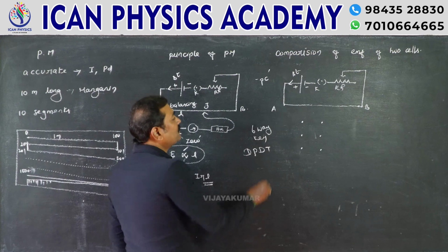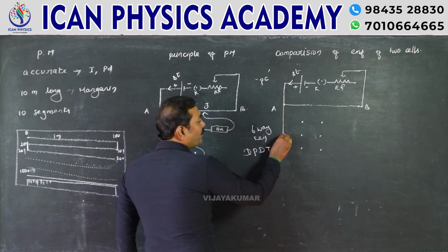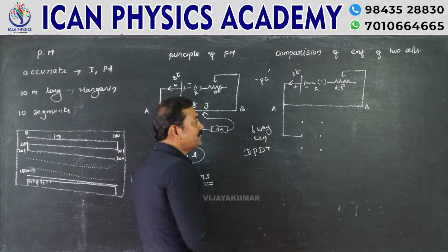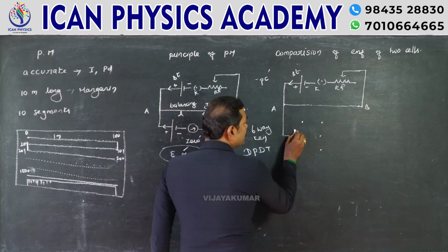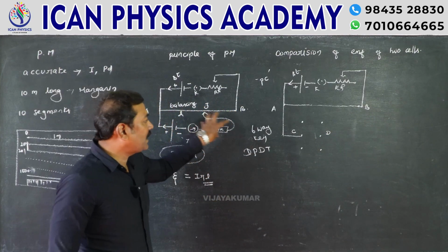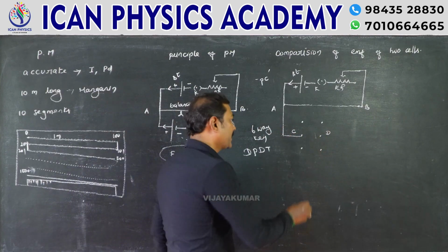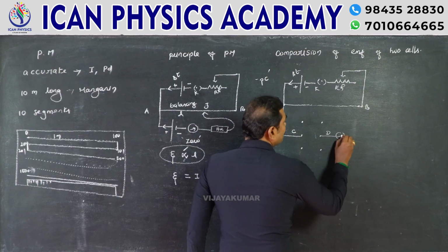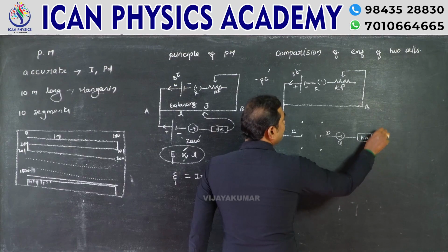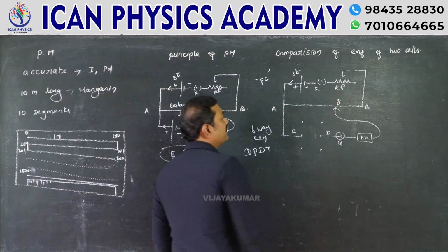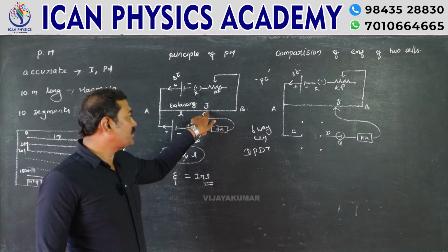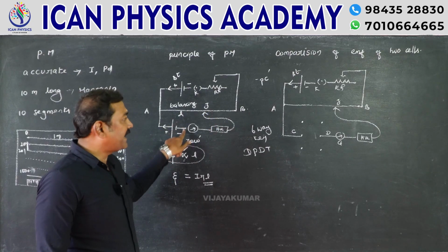Okay. So from the terminal A of the potentiometer, it is connected to the middle of the DP-DT switch. So A, B, C, D. Now take this part and connect it here. How? It is connected with a galvanometer, a galvanometer connected with a high resistance, connected with a jockey. So galvanometer, high resistance, and jockey have come. Only one is missing. Who?